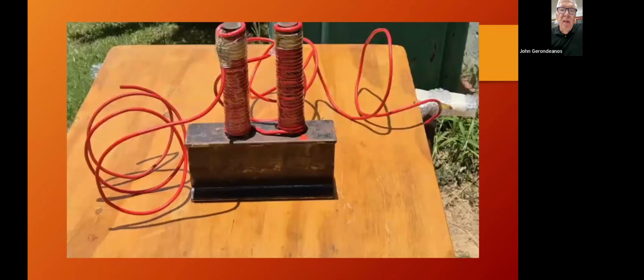So this is a magnetizer that's been built by Sean Painter. He's got pretty much 30 turns on each side there. It's 2.5 millimeter square household electrical wire. He's used a drive shaft from a Ford that he's cut to size and a piece of I-beam. And he's dimensioned it so that it fits the magnet well. And he drives that between 60 and 100 amps with his DC arc welder.